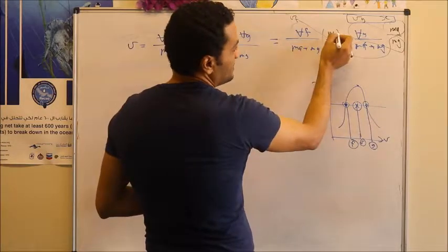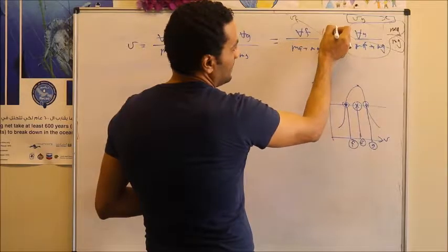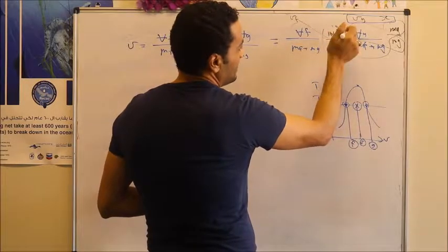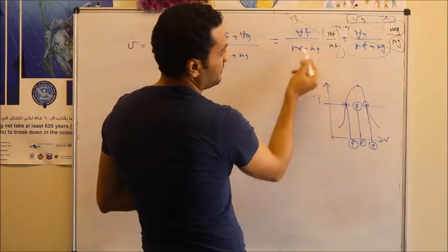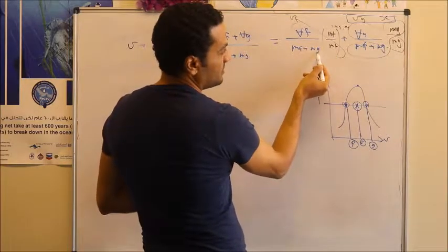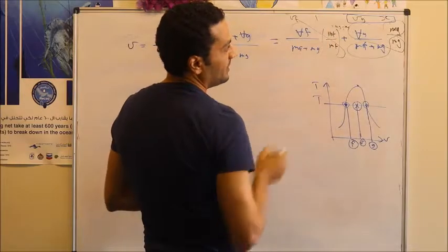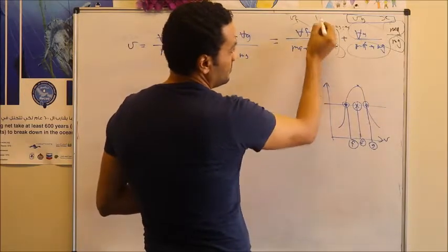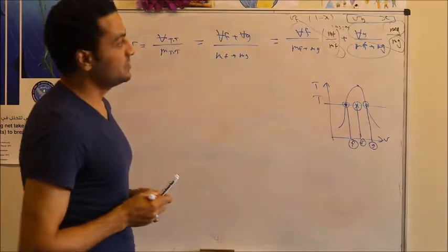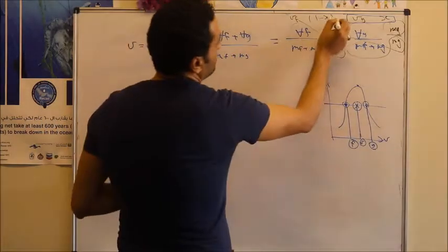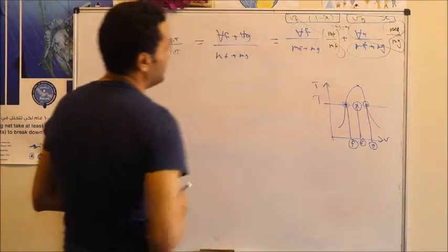So it will equal, just add mass of gas minus mass of gas. Mass of fluid plus mass of gas divided by mass of fluid plus mass of gas represents 1, minus mass of gas divided by the total mass, which is X. So this term will be 1 minus X. So the whole of this term can be represented by V fluid multiplied by 1 minus X.